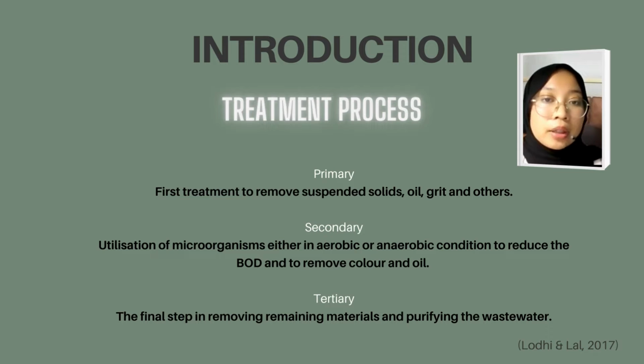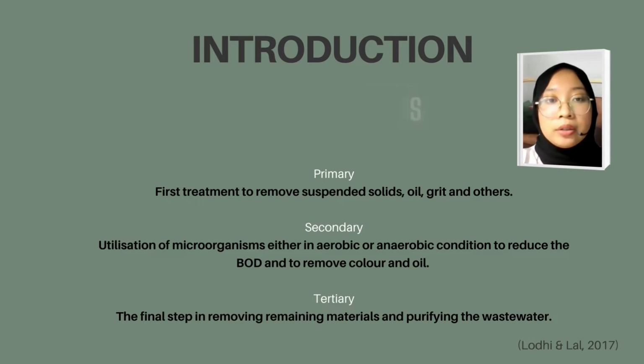The first treatment is the treatment that acts to remove suspended solids. Then the water will flow into the system until it reaches secondary treatment, where usually microbes are used to reduce the BOD and remove color and oil. The last step is an optional step to further treat the water from remaining contaminants to produce purified effluent.